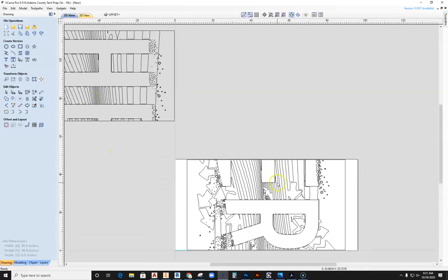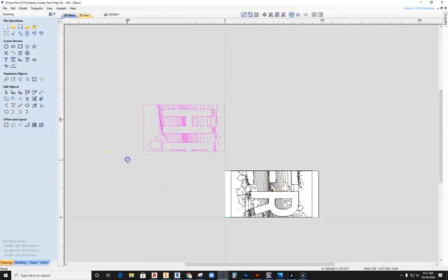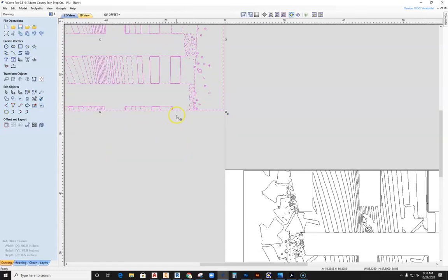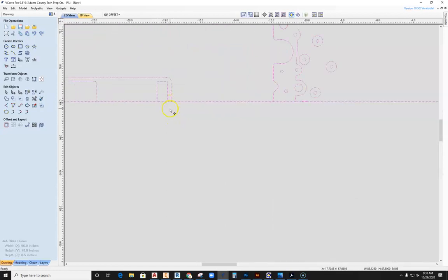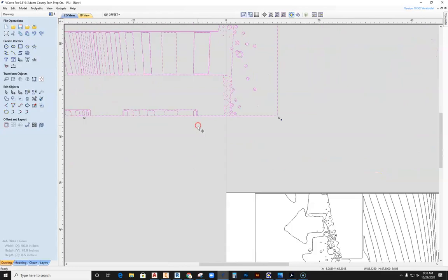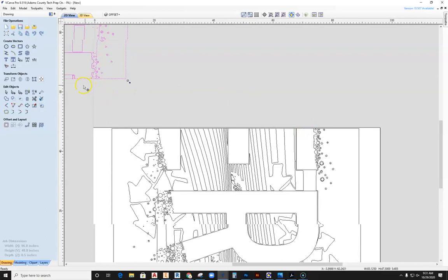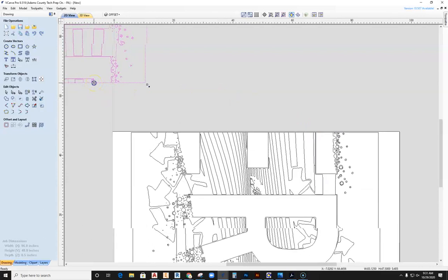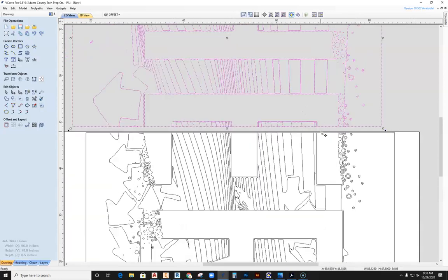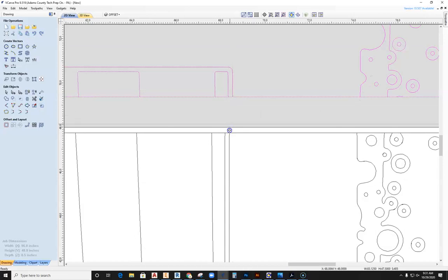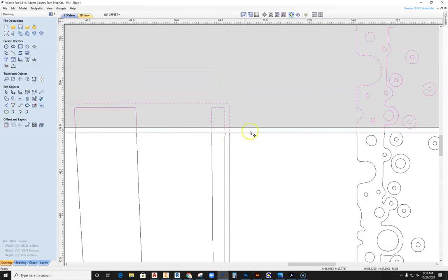After you do set these in position, then what you will do is you're going to take the panel that it meets up with, and then you'll select that panel and grab it from a piece of geometry that it's going to match up with. So here, I'm grabbing it from where the E is going to match up with the E, and I want to take and move it over to where the E should actually match up with this part. Okay, so I'm finding that location. I'm going to drag it over, get it closer, and then I start zooming in, and I'm going to take it by that location again, and then lock it onto the mating panel.